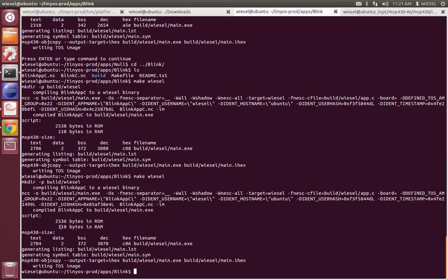So the next step would be to actually program our MSP430. Now we are using an application called mspdebug, and mspdebug supports pretty much all the MSP430 programmers out there. The one that I really like is this small little EZ430 UIF. This was from the Easy Chronos programming development kits. There are a lot of different ones out there. There is one from the RF2500 and one from the EZ430 RF2013. Unfortunately, all run different software on them, so either you upgrade the older ones to a newer software version or else they won't work.